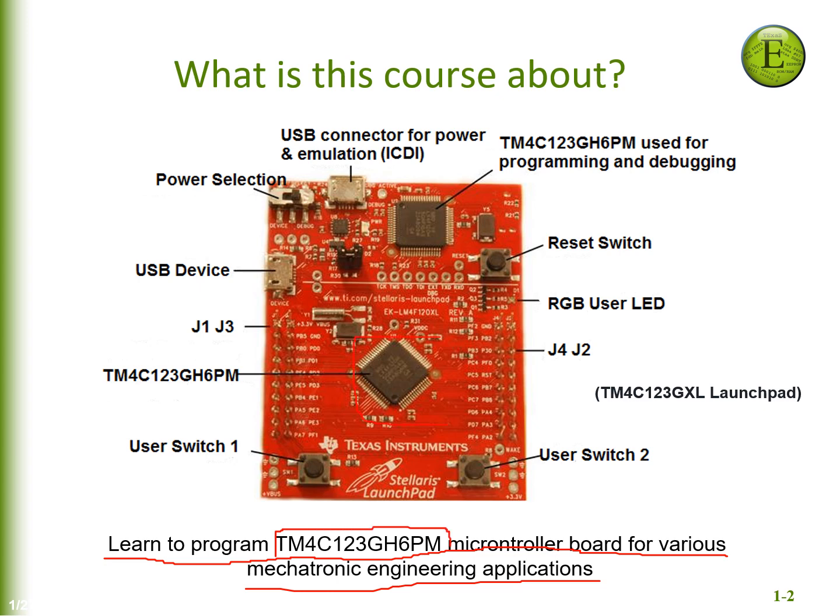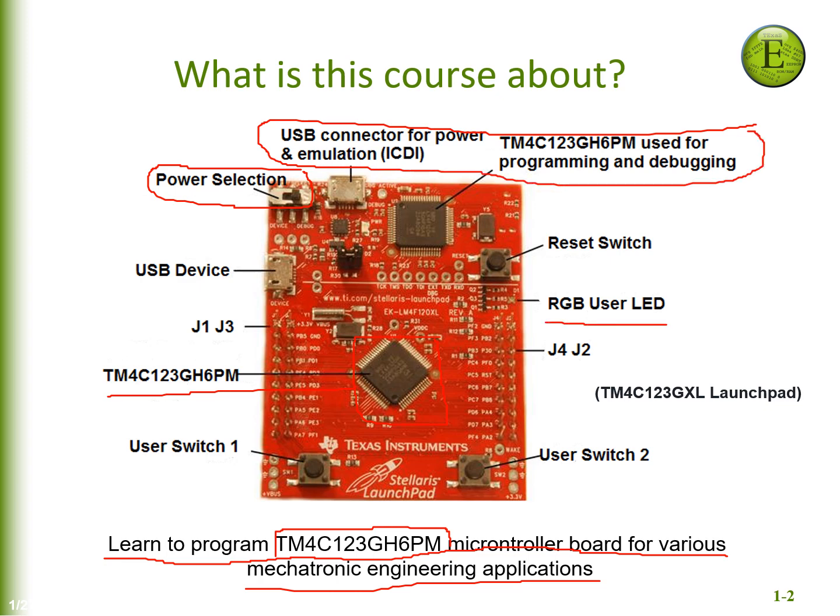The microcontroller is TM4C123GH6PM, which is this chip shown here on the diagram. However, for the sake of application development, the microcontroller doesn't come alone. In fact, it comes with a complete package containing complementary electronics, such as the power management switches, the debugging interface, some displays in the form of LEDs, some switches, and large number of input-output port pins. And that's where we connect the external devices to be controlled and run by the microcontroller. And all of these things are integrated on the single PCB, and they are together called the launch pad.